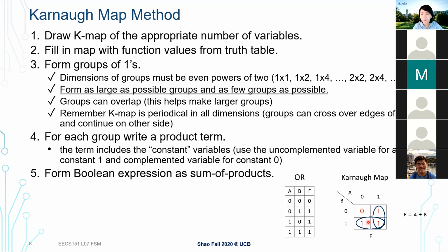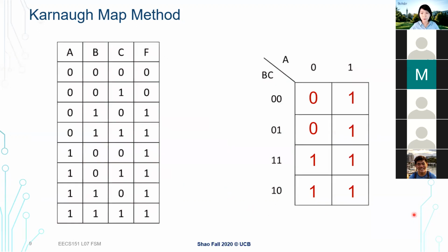And this is basically an OR gate for this example. You probably already did some exercises in the discussion, and we'll have more exercises to help you get more comfortable with this. But the Karnaugh map is very intuitive in providing a graphical format to see what potential terms can be eliminated. A lot of the time it's a lot more intuitive than staring at the Boolean expressions, and it can be very useful for figuring out simplification opportunities.